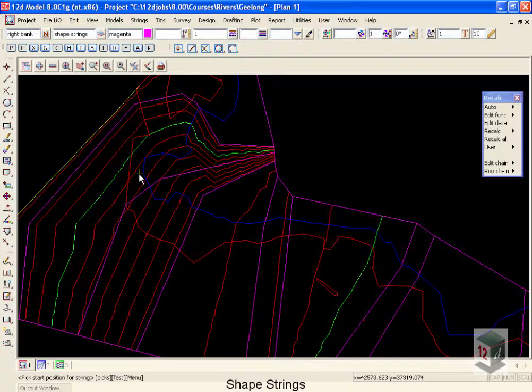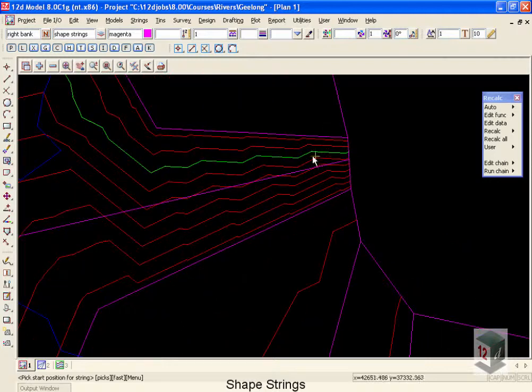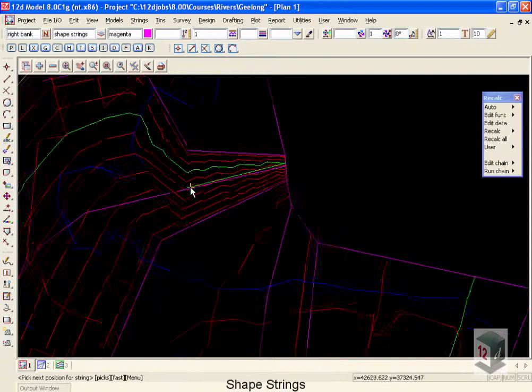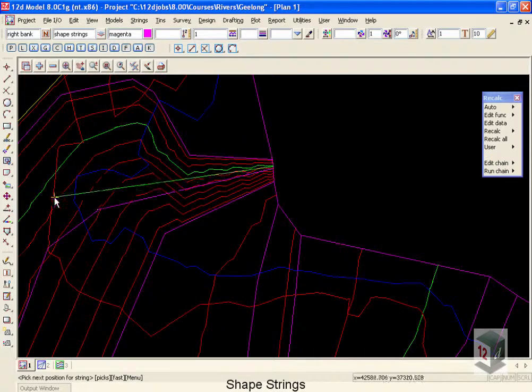Now what that is going to do is it's now going to have my tin sloping in this direction. But I'm going to have to do that several times again, once for inside here, once for inside here, and then finally again perpendicular. Now that's going to make them quite close up at this end. So once again, I'm going to start back here. I'm going to bring that in. My plan is to come into about this spot here.